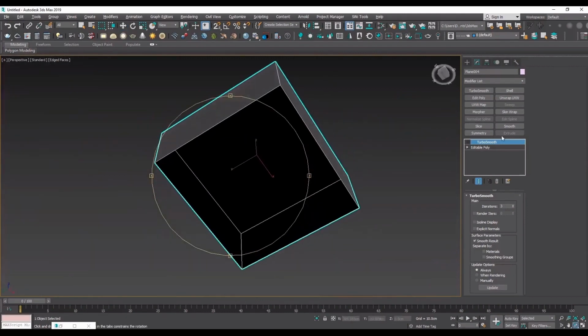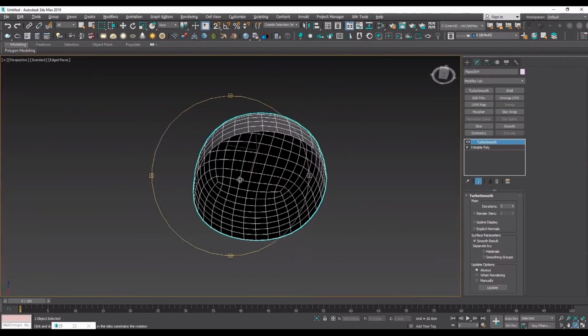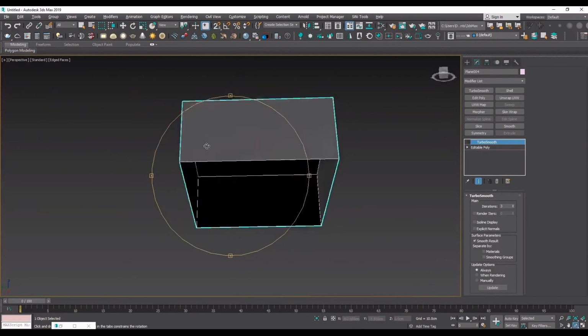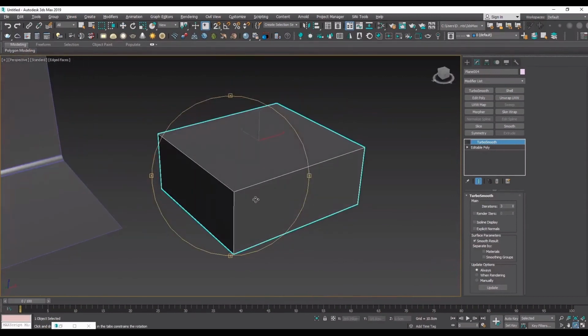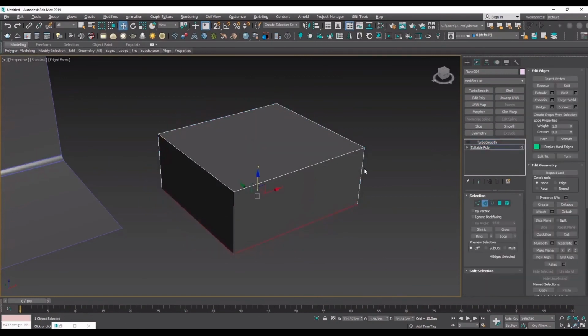Now to continue, I want to further limit the curve we get here. In the previous operations, we used extrude and chamfer, but here we can do other things to add an edge loop across our model. We can either select this edge and then press ring select, then connect to get a new supportive edge and move it up, or we can do completely another thing.